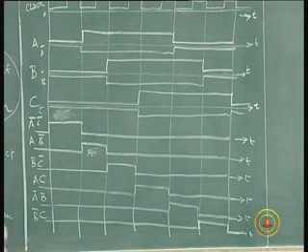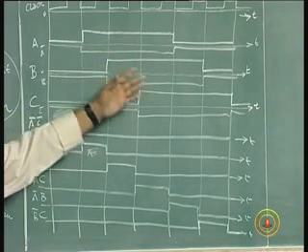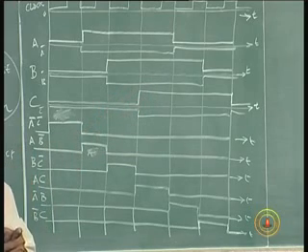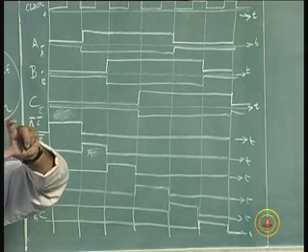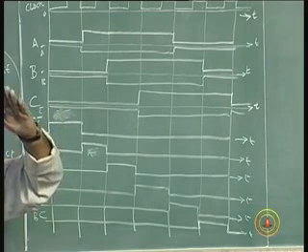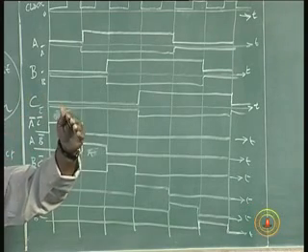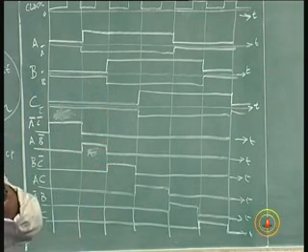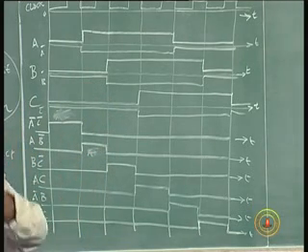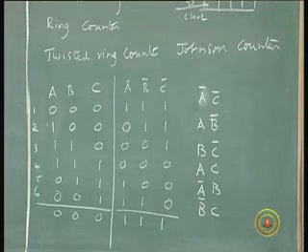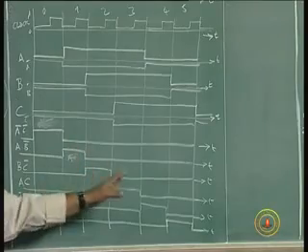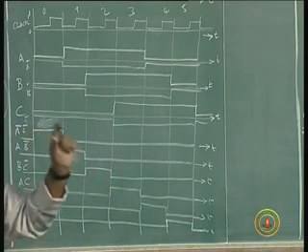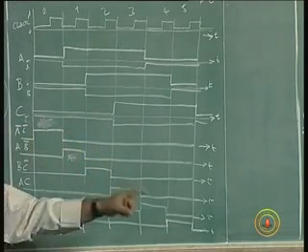So I have now a variety of choices. I can either have a 3-phase clock with the same period of 6 times the original clock period. So I can have overlapping lights: 3 lights on, first light will be on, second light will be on after some time, third light will be on after some time, and then the first light will be off, second light will be off, third light will be off. That type of display, if you want, you can have it. Or I want to have only a light on for this period, first light, and then it will go off, then second light will be on, then third light should be on. They have 6 lights which should be on for 1 clock period each of the original clock, and then again it will repeat.